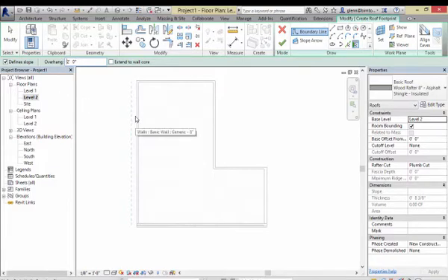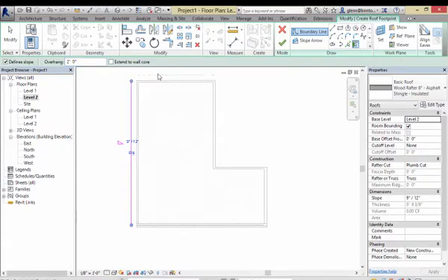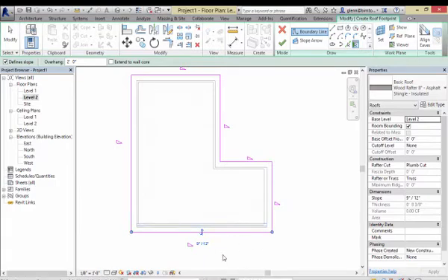And I will click on those different walls. Notice as I click on the wall or hover over the wall, it suggests which side it might be on. I'm going to click on all those walls and hopefully get a nice continuous boundary. Ultimately, very much like the floor, we need a continuous boundary.